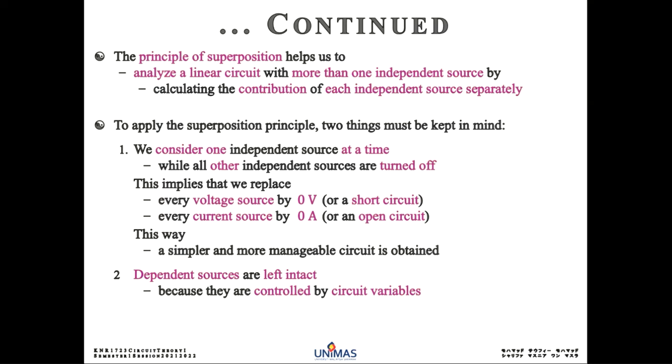The voltage must be 0. How do we do the voltage source? I've already mentioned so many times. How do you want to make the source 0? We apply a short circuit, because for a short circuit, there is a current, but there is no voltage.